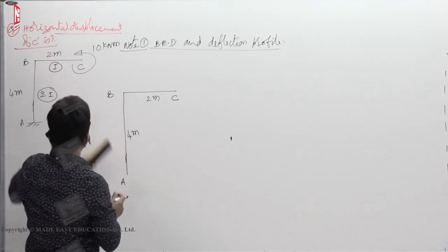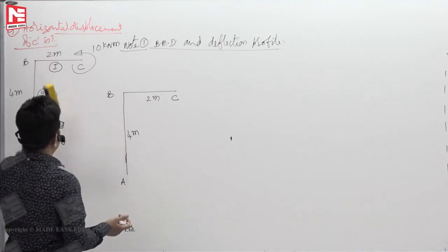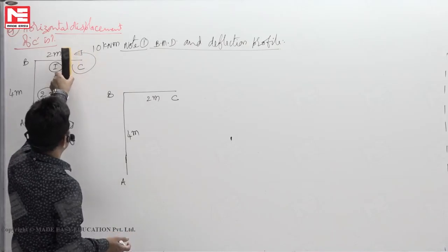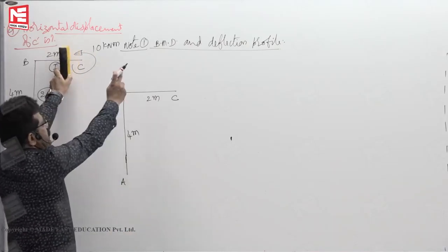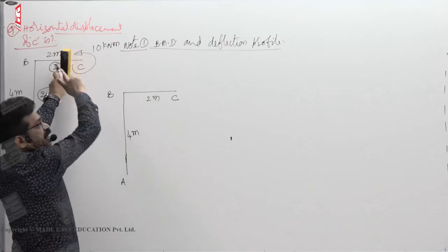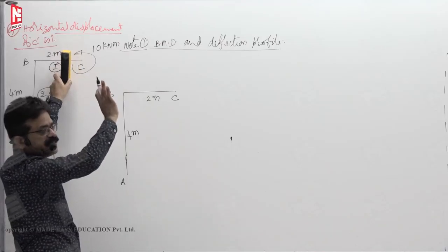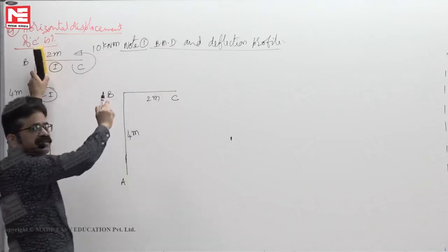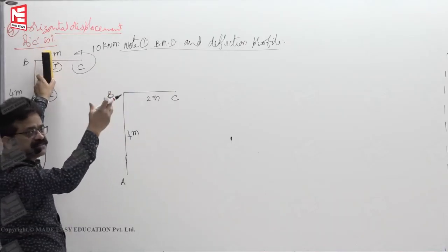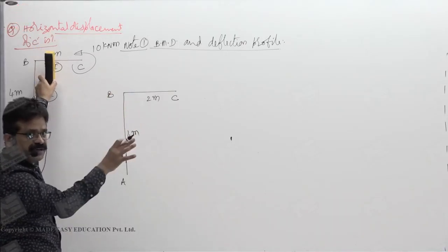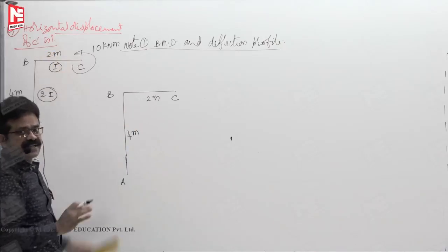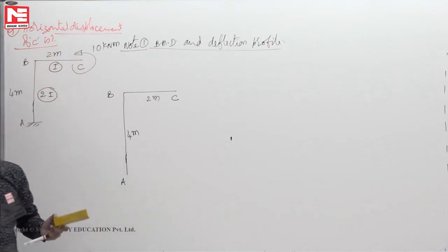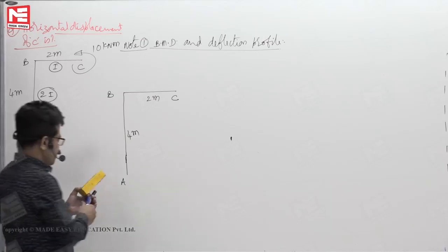Now you see, to draw the bending moment diagram for any member, what we have to do is stand here, look right side, section right side anti-clockwise 10, so plus 10. Stand here, look right side, again plus 10. If at two places you stand and find the moment, if it is equal, it means that the bending moment is a rectangle. That means it is a pure bending moment case.